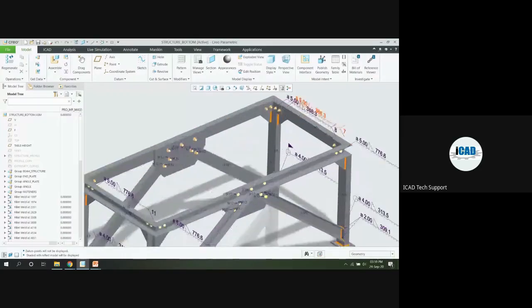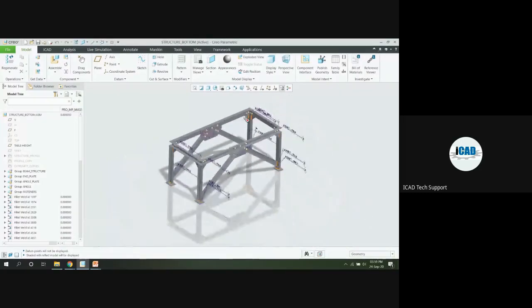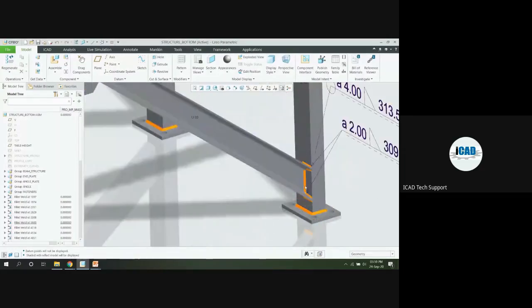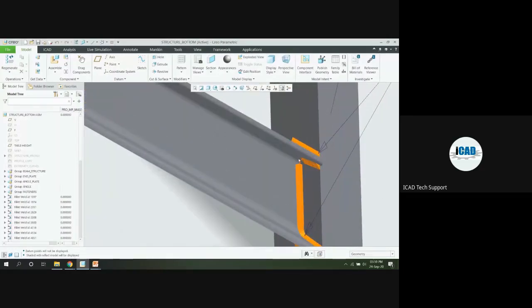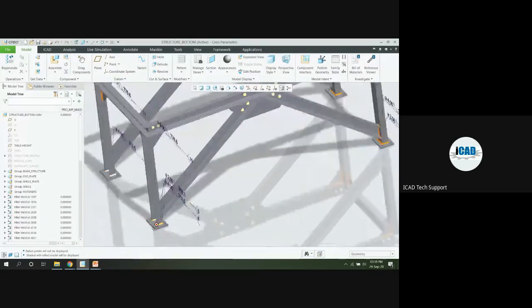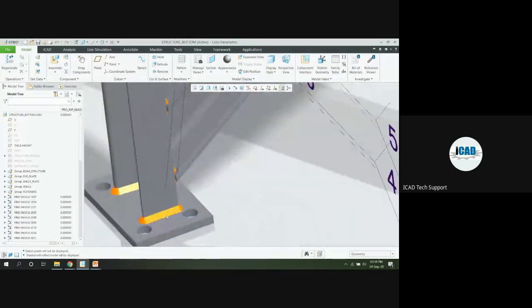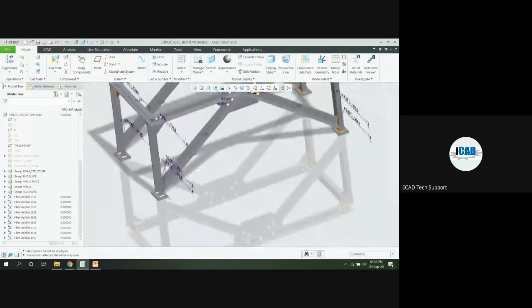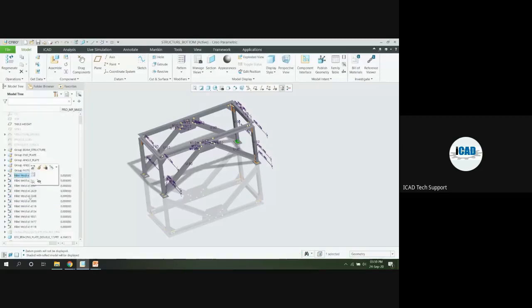By using this structural assembly, we need to add the fasteners and these weldings. You can see I have given these welding symbols here. At the bottom surfaces, the connecting plates we need to weld with the legs of that table. So how can we create these weld symbols? I will show.